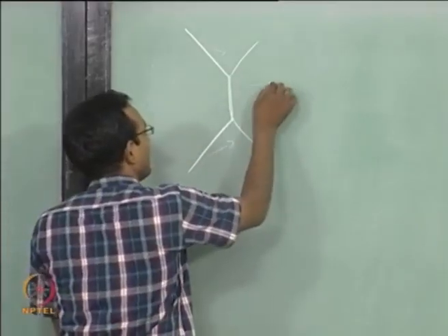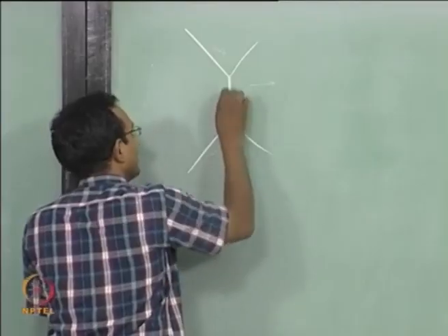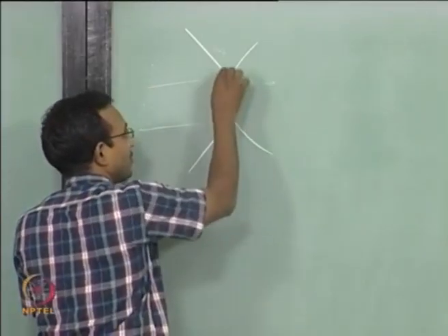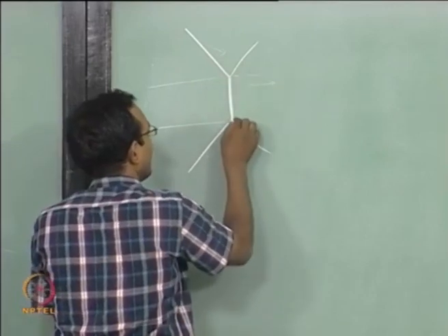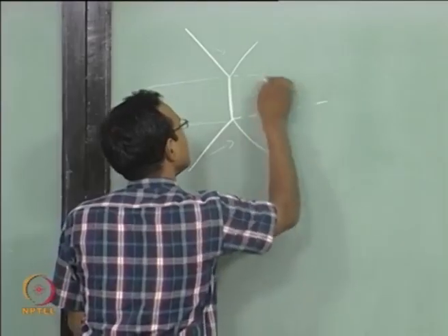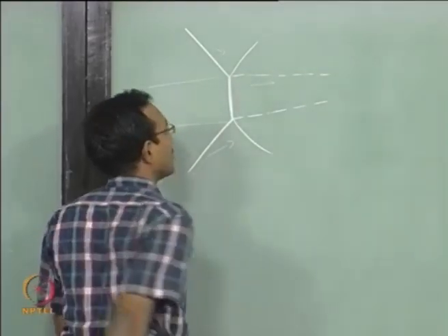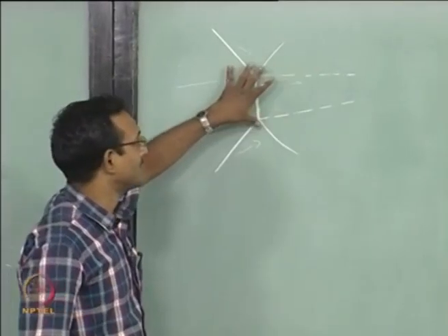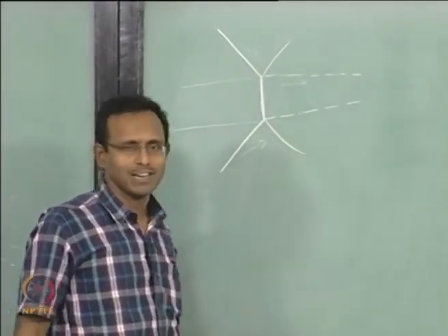Okay. And after that, it will have a normal shock in the center, flow that is coming inside this region will just face a normal shock and it will go this way, and there will be two slip streams this time. Two slip streams, and they need not go parallel to each other. Okay, I have just drawn it such that it is converging, most likely it will converge.